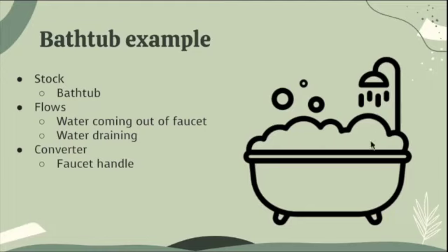And so once we have our model all built in our system dynamics modeling software, from there we can simulate this bathtub by using some initial conditions and then running through our differential equations for our desired time span to look at how the stock, or the amount of water in our bathtub, might change.